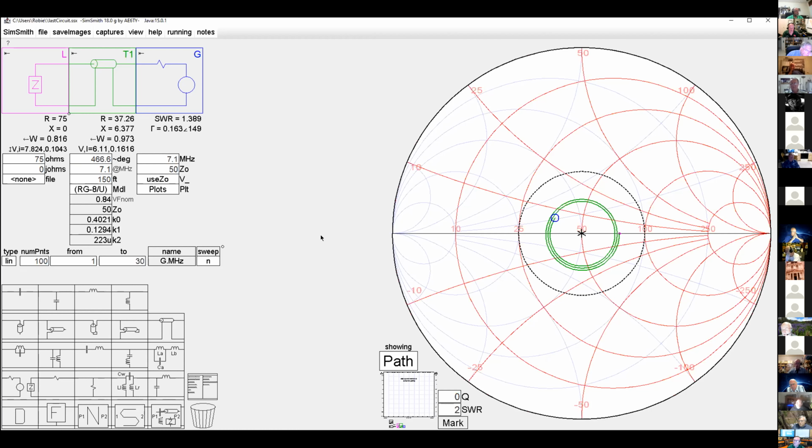Now, I can shinny up the tower once I get the antenna up and put my VNA right at the antenna, maybe, and that would be one way to do it. Or I can put up the antenna, connect the transmission line, and I'll show you how to make a set of measurements where you can tell what the impedance of the antenna is by measuring the impedance at what the transmission line shows you, at your transmitter. So that's one of the examples I wanted to work through.